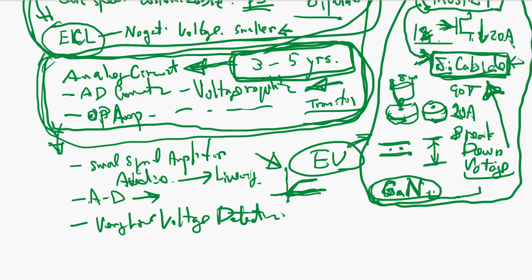Like a battery, you have to know how much current is going through the battery, and in order to do that, you have a 0.1 ohm, very low resistor. You don't want to put too much resistance; there's a voltage drop, and energy consumed by this resistor. This is the current sensing resistor, very small. So the voltage across it is quite small, but when the battery is charged up, the current decreases.